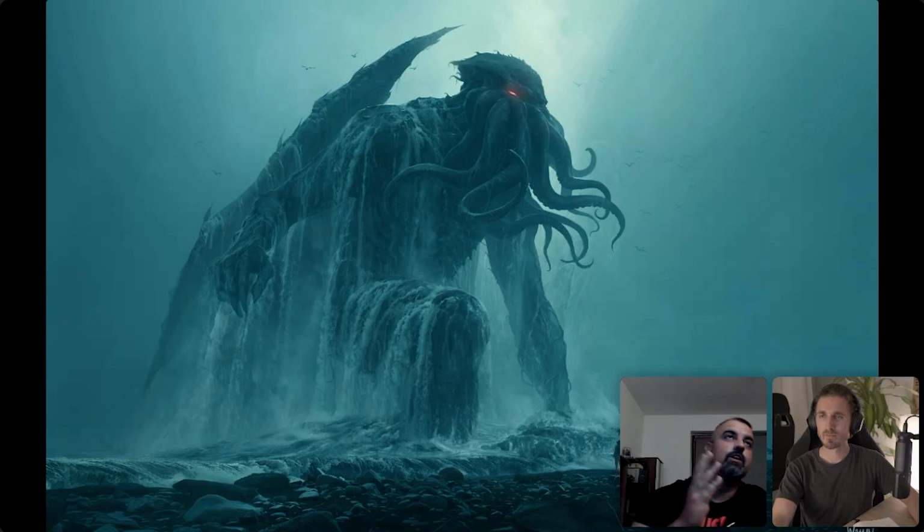Sometimes values 2 and 6 will work, like he wrote on 0.1, because the details in a splash will be more combined. Velocity smoothing in a FLIP solver can also help to break things up even without using crazy droplets. So it's a mix between particle separation, velocity smoothing, and droplets. This mix can sometimes help you even with going with the lowest settings.